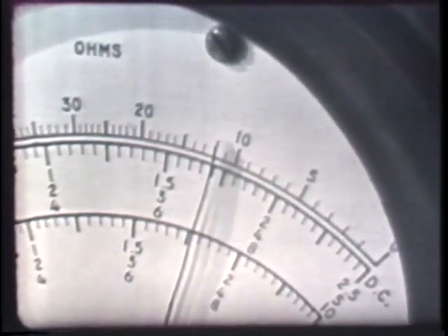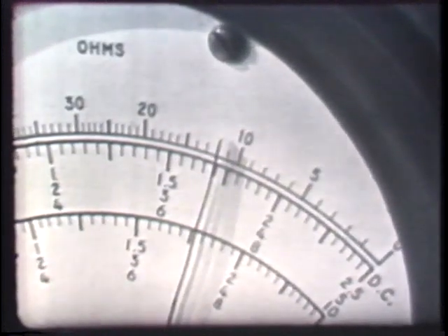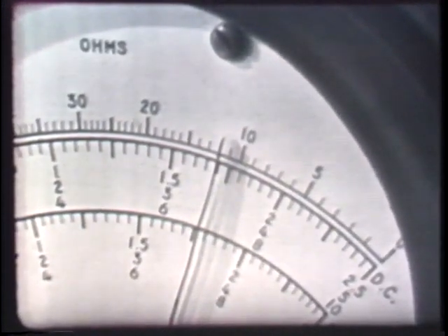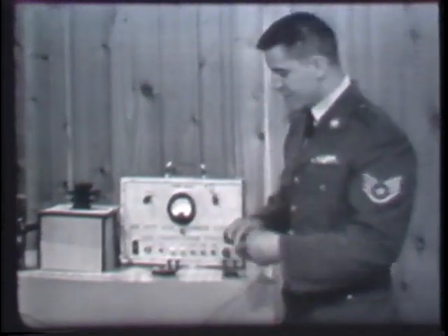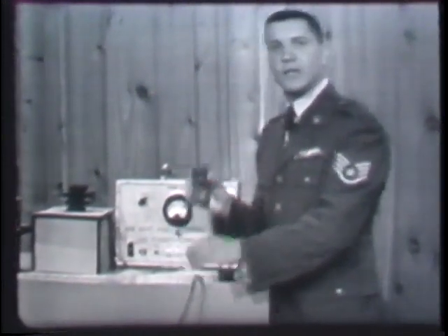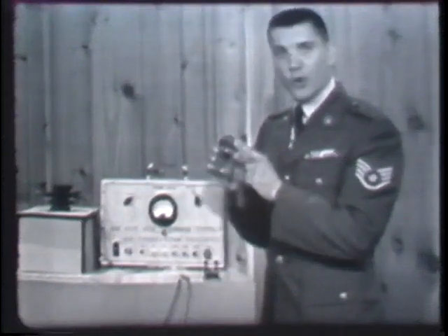But we've already pointed out the normal resistance of the 300 turn winding is 20 ohms. Thus, we can conclude that some of the turns of this 300 turn winding must be shorted. As a matter of fact, I've already figured it out, and approximately 70 turns of this 300 turn winding are indeed shorted. Now we see then that for a shorted transformer winding, the ohm meter will indicate a resistance less than the normal resistance of the winding.